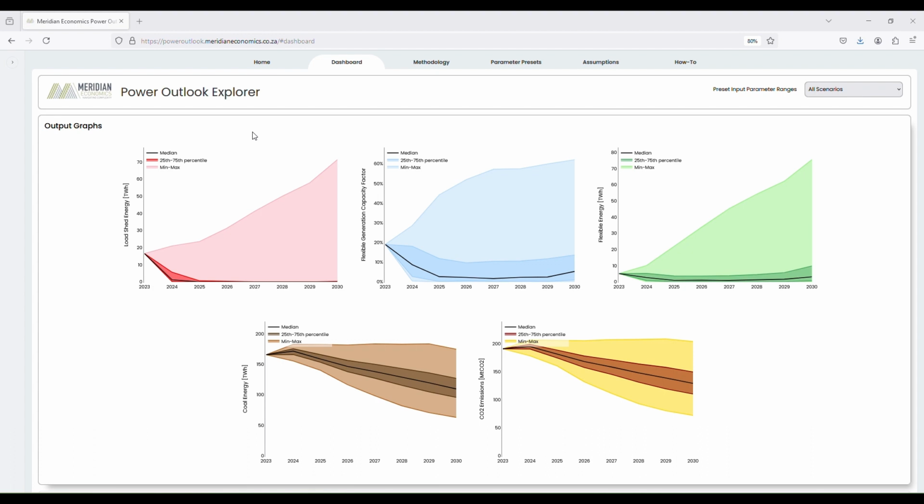So at present, that's the open cycle gas turbines. In future, that capacity could be gas-fired, open cycle or combined cycle gas turbines. That capacity factor, one would like to see below about 10% in a healthy power system. That's the most expensive generation that's on the system. And if things are working well, you're not using that to generate that much energy.